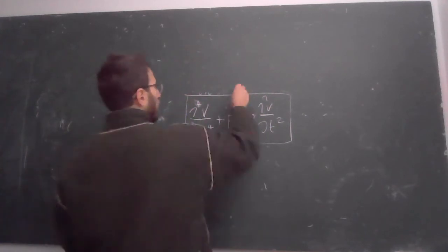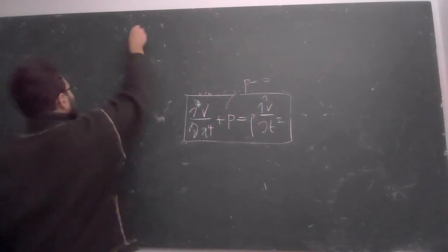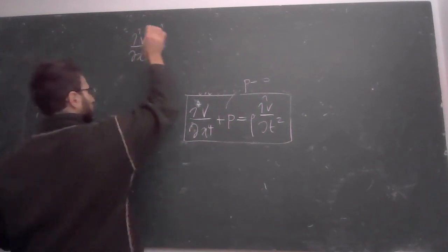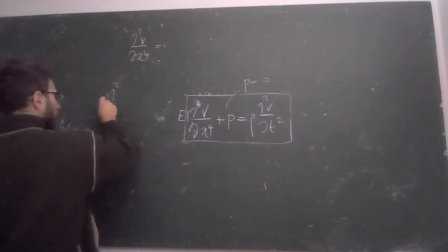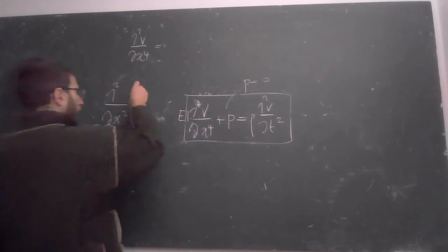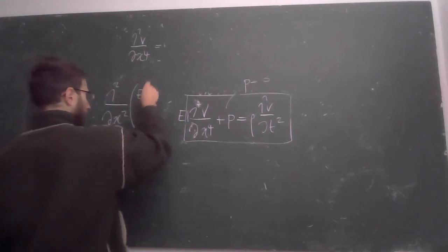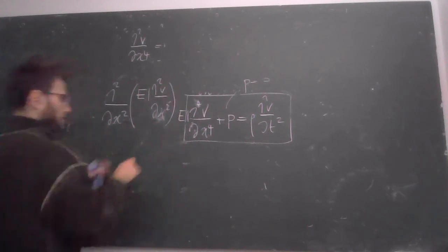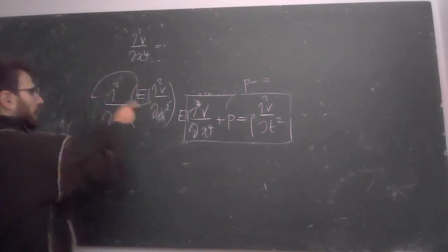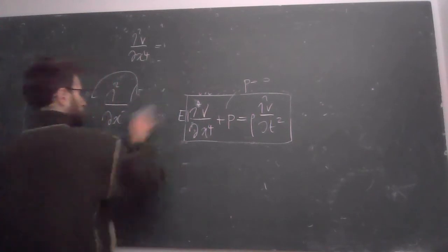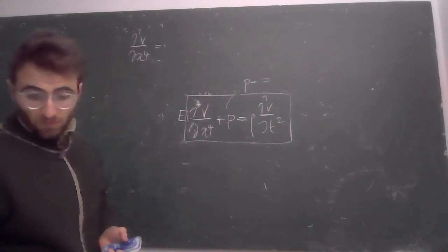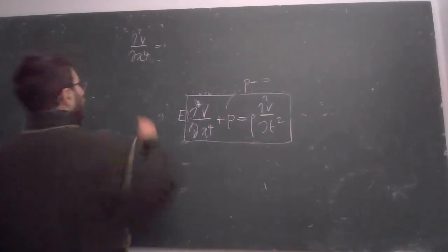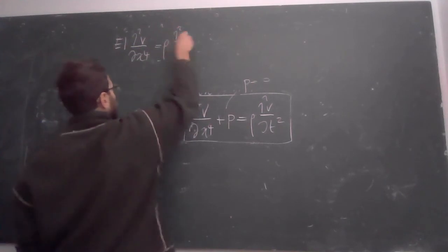If we consider the homogeneous equation, so we assume that there is no external load, the equation becomes, I forgot EI. EI stands outside if it's constant, because we had d square dx square of EI, right? It's constant, it goes outside, and we have this equation. So the fourth derivative of v over dx fourth times EI is equal to rho d squared v over dt squared.